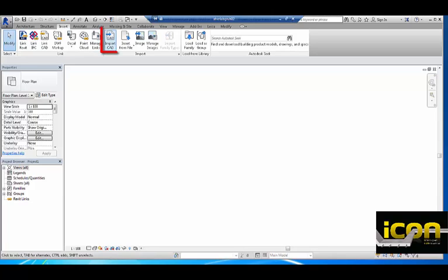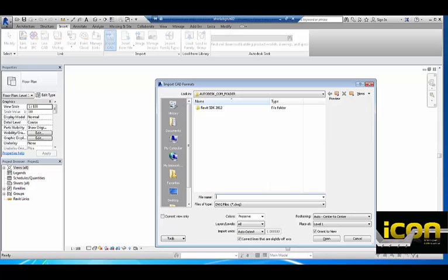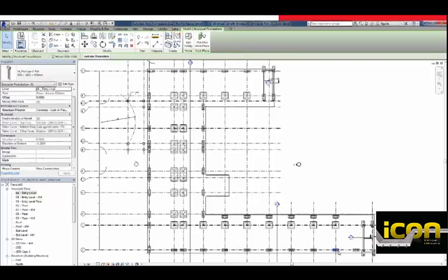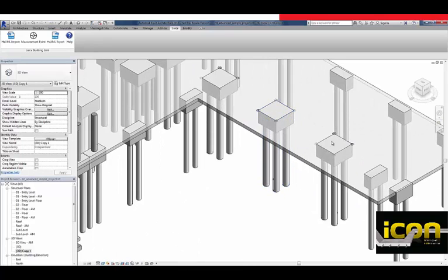Using Revit once more, I import this DXF file back into the model. It includes all field measurements, setup observations, but also my staked and measured points previously done in the field. As I've imported all my field measurements, I can compare these visually with the design model.